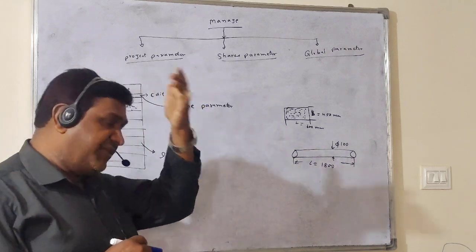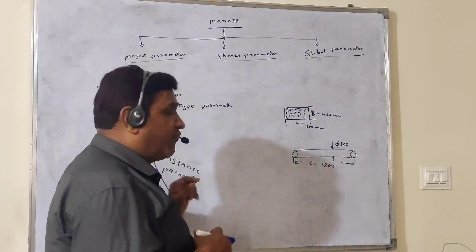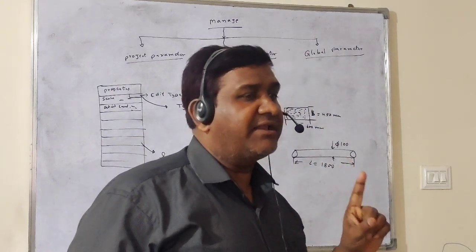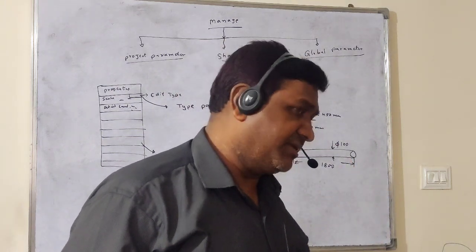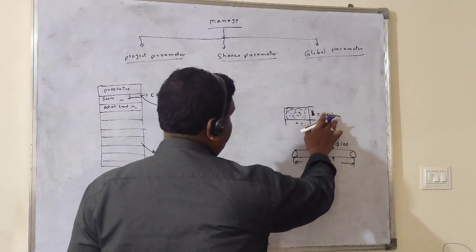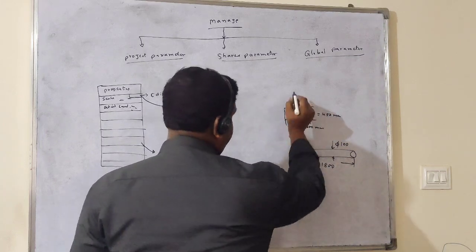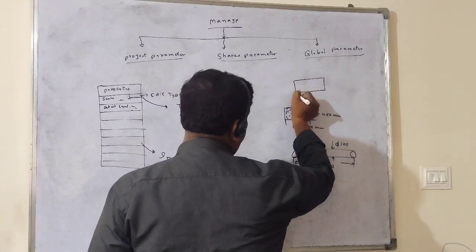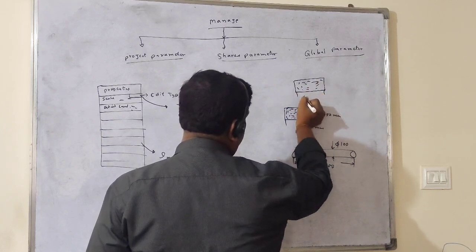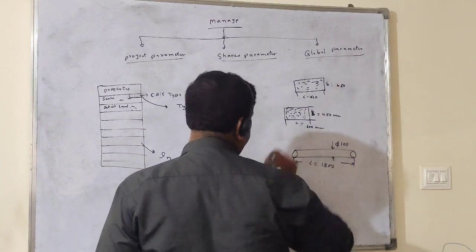Here is why I am telling you the difference, because of this example I just showed. The parameters that we change individually, we will call instance parameters. Just an example: now your column length is 600 and width is 450. The same column you have placed again somewhere else in your model, and again there the length is 600 and the width is 450.